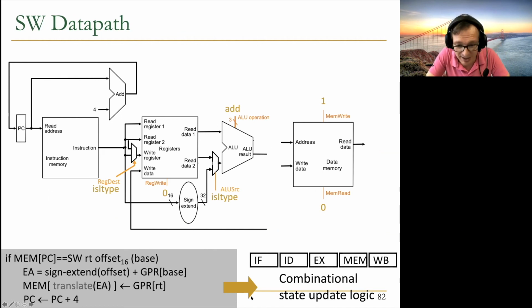So let me actually annotate over here so that you see clearly. I should change the color also maybe. So let's do it over here. Basically, this is our address, ALU result, and we need to get the data from the register file and write to memory, right? And we're not reading from memory, so this doesn't need to be connected anywhere for the store.